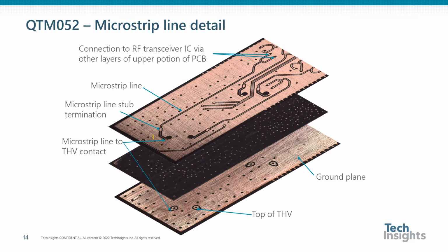These images show a detail of the microstrip line that connects the patch antenna to the RF transceiver. The single-ended line is routed to the transceiver, where it splits off and connects to two pads on the transceiver die, the TX and RX ports as it turns out. There are two lines from each of the patch antennas, hence dual phase.